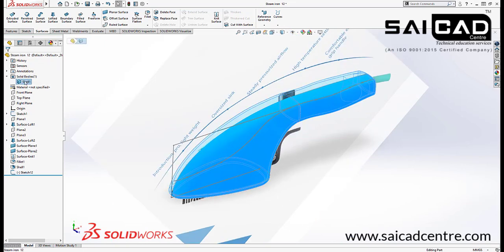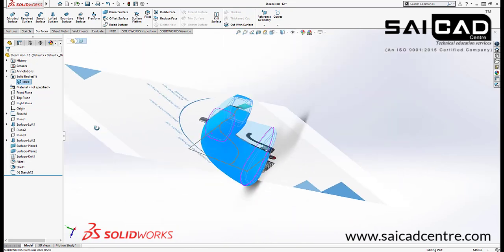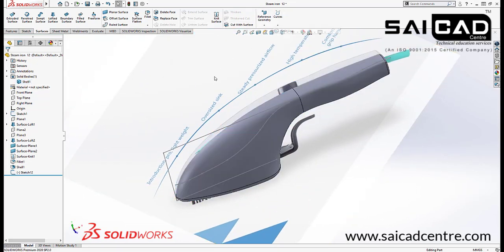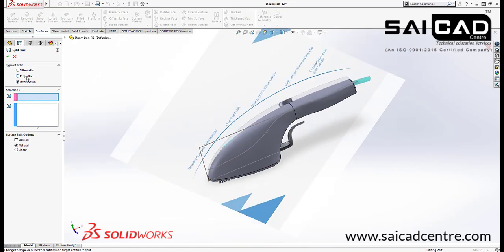So you can see that we have the solid body here, shell 1. I need to split that body. So go to the split line. Now in the split line we need to select the face or body to split, and first we need to select the sketch. Okay, so with the help of the sketch we need a projection option. So I need to project this one, and here we have the option only to split the faces.